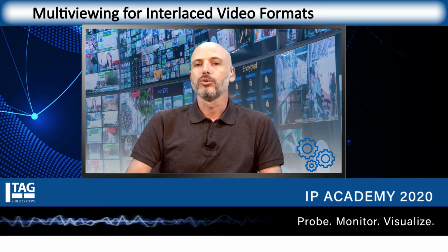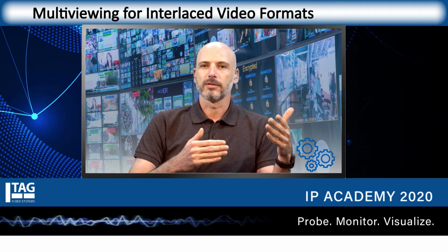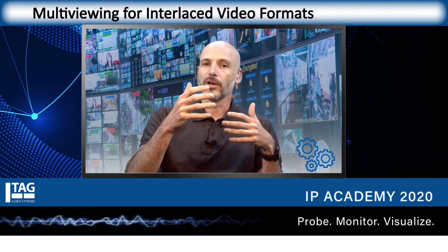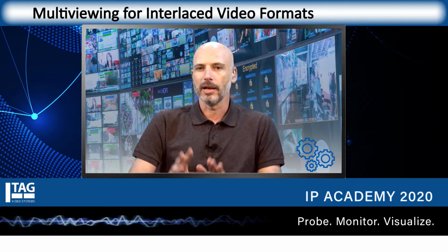So how to do the de-interlacing? There are different methods how to do it. In the end, we're talking about having two fields encoded at separate times. So we have the odd lines of one timestamp and the even lines of another timestamp. So the camera is taking a picture of a different content in those two times. This is why you see the lines in the football game twice. And for the de-interlacing, there are lots of different algorithms.